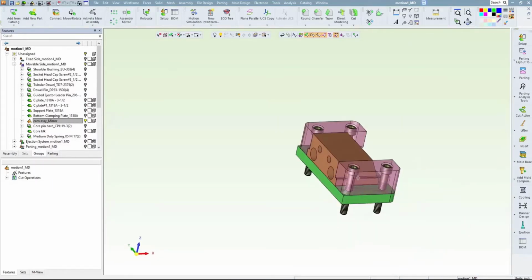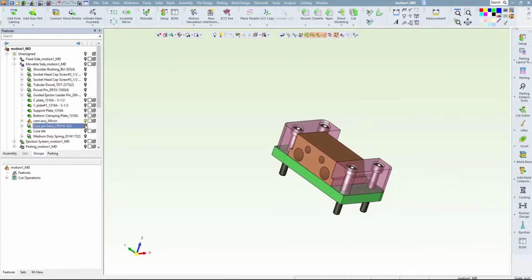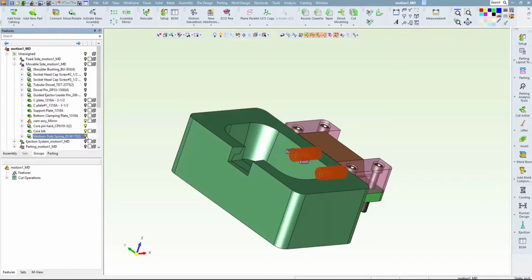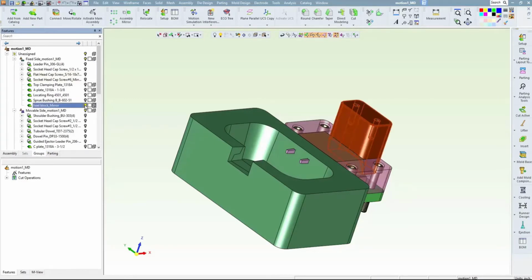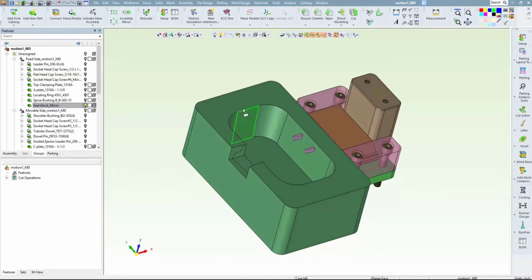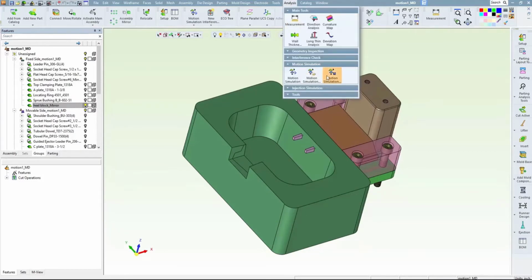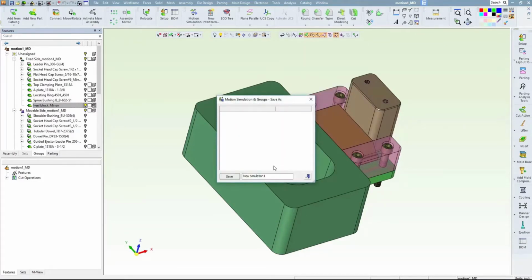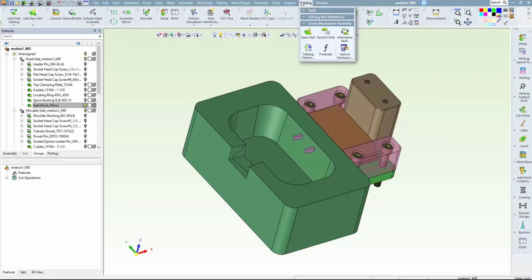Let's switch to a different example in order to discuss springs. The motion analysis tool can recognize coil or gas springs as an input force on the mechanism, but they have to be correctly defined. Prior to making a new simulation in the same assembly, the previous one should be saved with a specific name. Saved runs can be loaded again later, or a new run started.